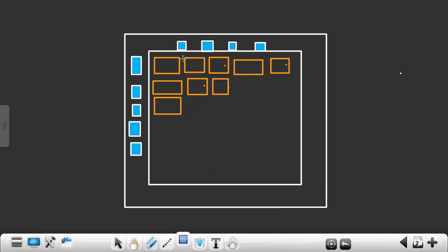After placing macros, apply the blockages in the macro channel. This is placement blockage. Apply it wherever you want, like partial blockage or soft blockage. Any blockage you want, you apply it in the macro channel.